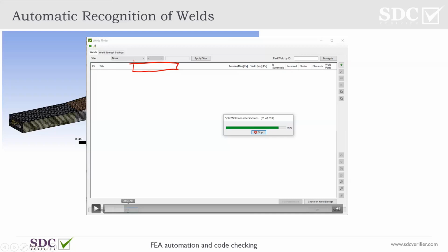So in order to do it, what data would you require from the existing cranes? Yeah, that's a good question. Basically, we need only the typical input data according to specs. So what are the speeds, accelerations? What are the weights of the crane? Because weights determine the COG of your crane, which creates a different distribution of your stress level.